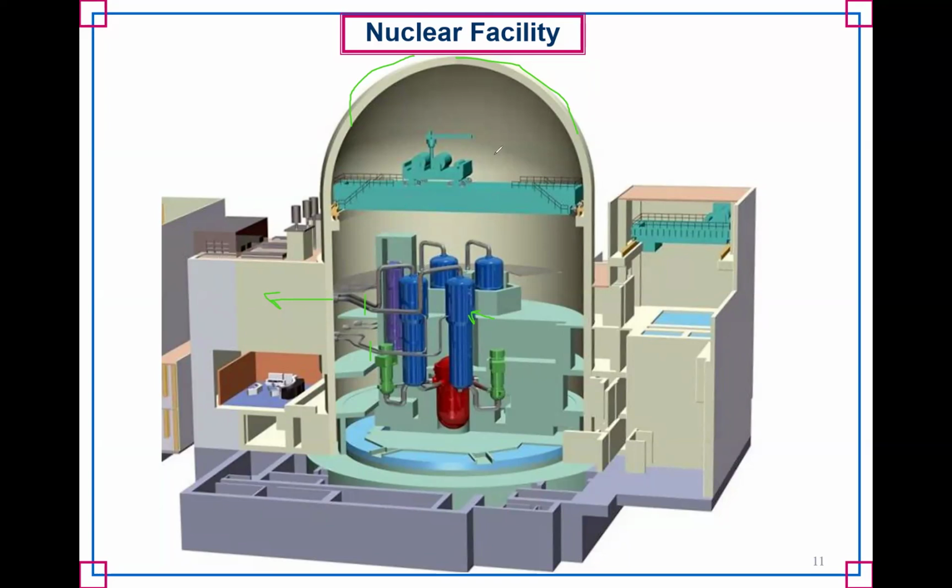So inside containment, the pressure gets really high. The whole idea behind the design of a containment structure is that if those pipes break, the size and strength of the containment structure give it the ability to absorb all that high pressure steam that has been flashed, and it expands very rapidly, but the containment structure will not get damaged. The one at Maine Yankee was designed to go all the way up to about 50 psig, which is quite high. And they had to test it.